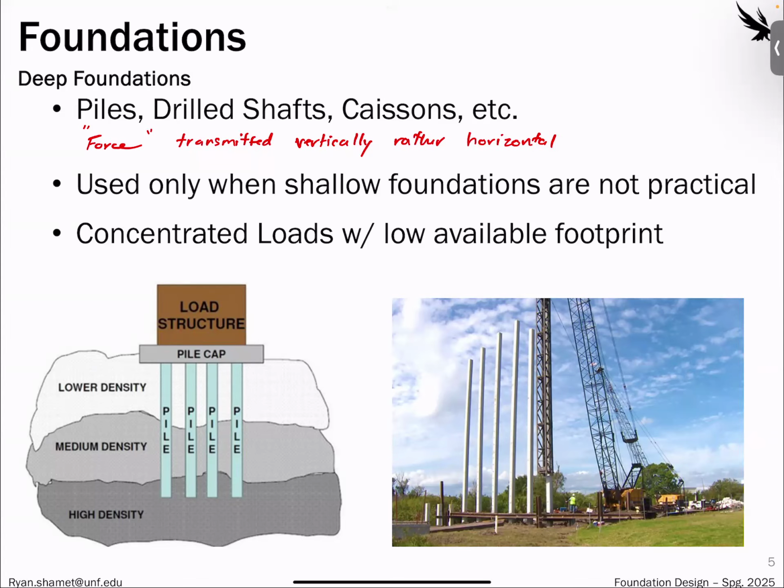So it's only used when shallow foundations are not practical, whether it be settlement or bearing capacity, or whether maybe the project doesn't have enough area for right of way and everything. Bridge foundations are often going to be driven piles or bored piles. Maybe you could also use these for ground improvement, like you see in this little photo here. Maybe you just have a 10-foot layer of crappy soil on the surface, and you do the cost estimate as a consultant and say, okay, you can either remove and replace all this soil, or it's worth the extra money to do the driven piles.